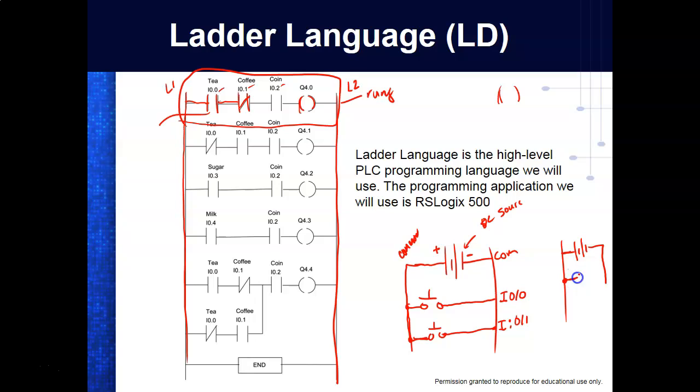And then this right here might be a light bulb. I'll hook it to my common, and then I would hook this up to output. Let's say output, that's an O, 0/0. So when this simulated coil, it's not a real coil, goes true, this output would put a 1 out and my light would come on.